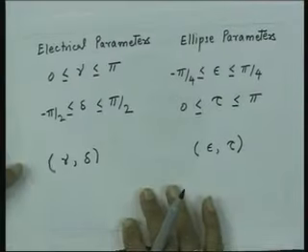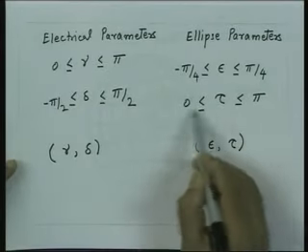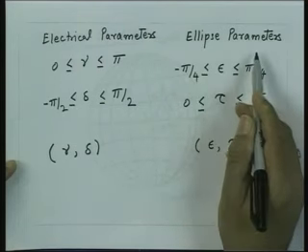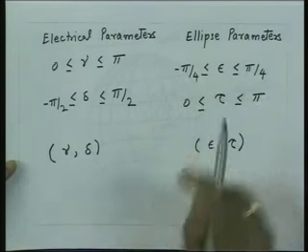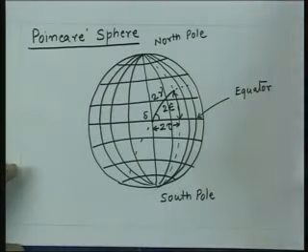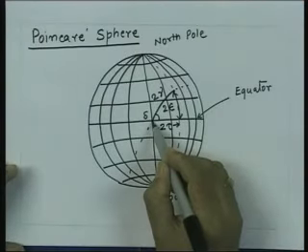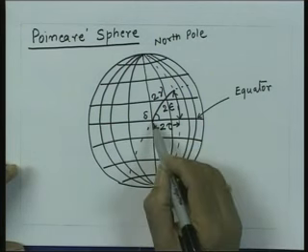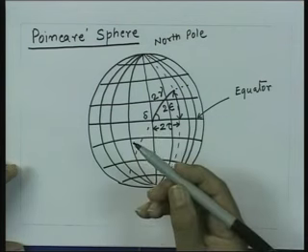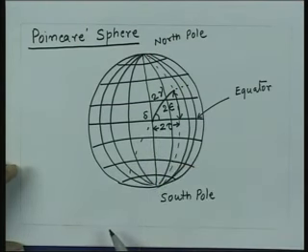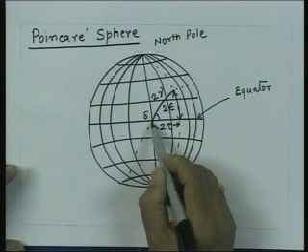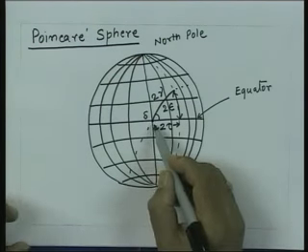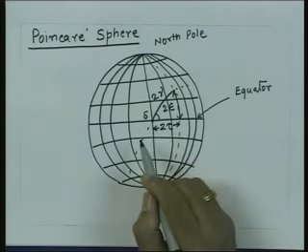Tau equal to 0 means the tilt angle of the line is 0, and epsilon 0 means the axial ratio is infinite. So this is a linear polarization with tilt angle 0, that means this reference point corresponds to the horizontally linearly polarized wave.